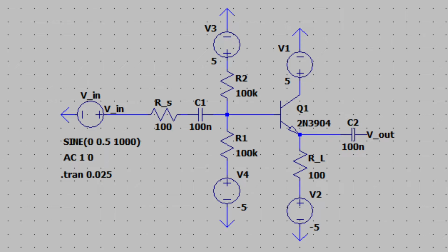Now that I have my Gm value, I can use it to calculate the internal resistance, which I use the equation which was posted in Project 3 Design Guide. This equation was Gm multiplied by RL divided by 1 plus Gm multiplied by RL, which is then multiplied by Rin divided by 100 plus Rin. And this should be bigger than or equal to 0.9 because we can only have a 10% attenuation.